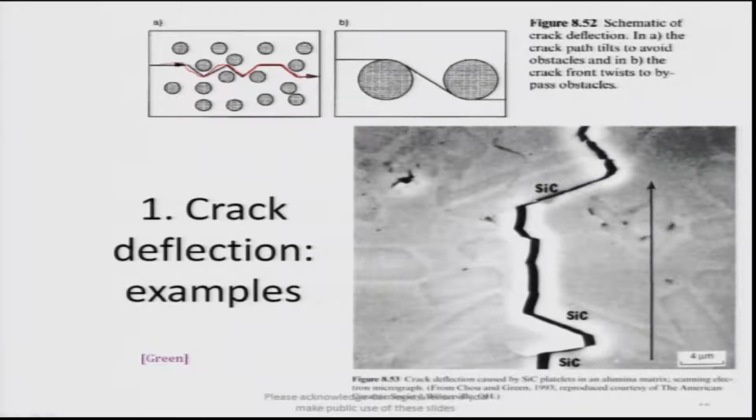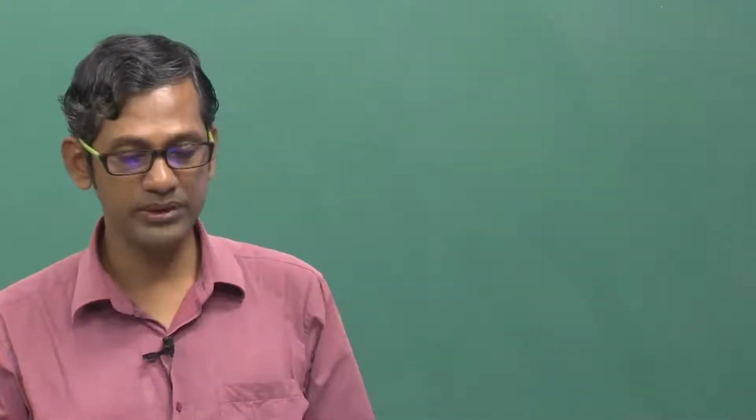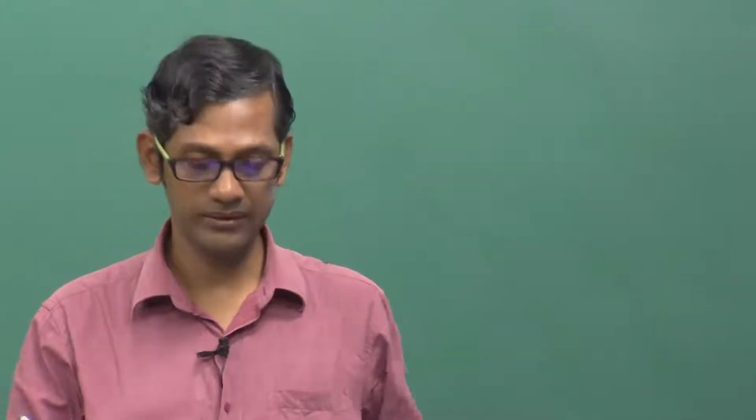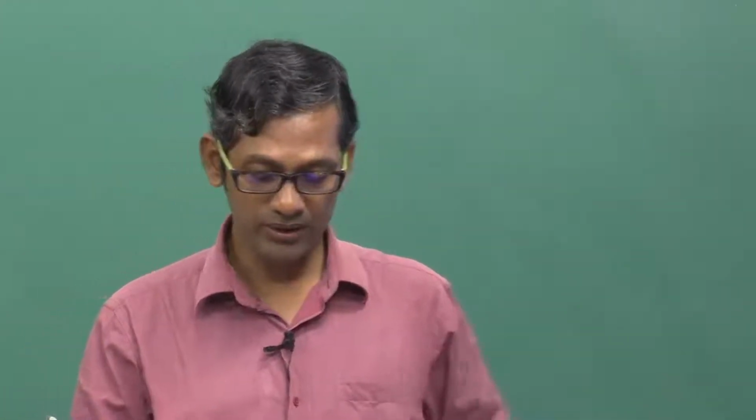It is bending and moving like this. When it goes through that, it means the crack requires more energy to propagate. We have to provide more energy to the system to do that. That means we can load the material higher, or increase the cycles the material can withstand in a typical fatigue test. So, that is one particular way of increasing the toughness.